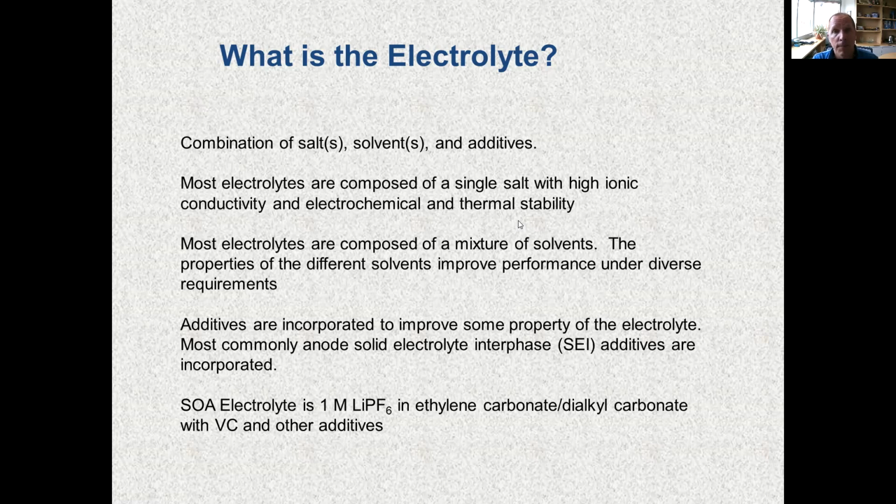Because once again, most applications for a commercial lithium-ion battery for consumer electronics devices, you're wanting the battery to last at least 4 or 5 years. And for electric vehicle applications or for grid scale storage applications, you're talking on the order of 10 years. In those kinds of applications, there may be thermal excursions by the car sitting outside, or just the charging and discharging of the cells, which can heat up the cells and cause long-term stability issues, which is typically referred to as calendar life stability.